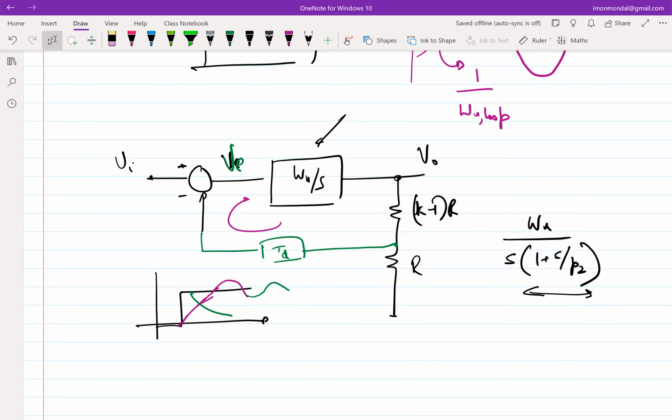And if you have a delay in the loop, the feedback can come later. In that case, you can have overshoots, undershoots, and in the worst case, some extreme cases, you might have instability also. So this is something I wanted you to leave with, because you shouldn't think that just because I have negative feedback, everything will track each other. Everything will track each other as long as your error information is coming on time. If the error information is not coming on time, then you have to take some corrective actions, right? We'll see what corrective actions you need to take later in this course, but not from this ideal delay perspective. Those things are left for 613.